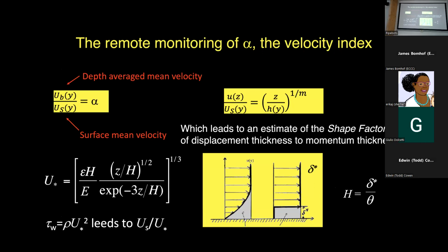And from there, we get after what I think has been a theme through at least 50% of this workshop's talks, the unknown quantity alpha, or the velocity index. It strikes me in watching all of you talk that we are easily making measurements of the mean surface velocity transect using STIV or LSPIV techniques at better than 10%. And once we get there, then the uncertainty in bathymetry and in the velocity index alpha become the leading order error.